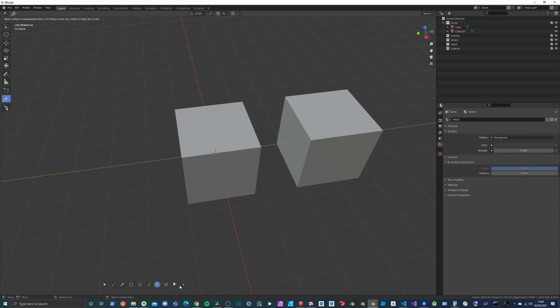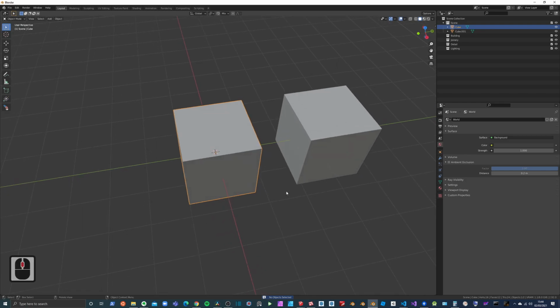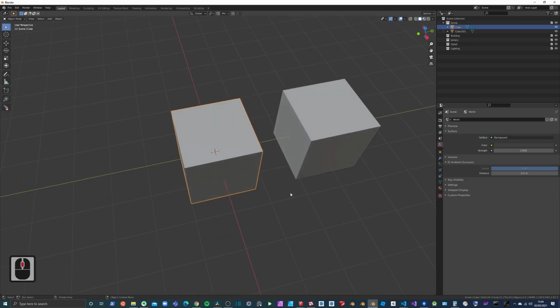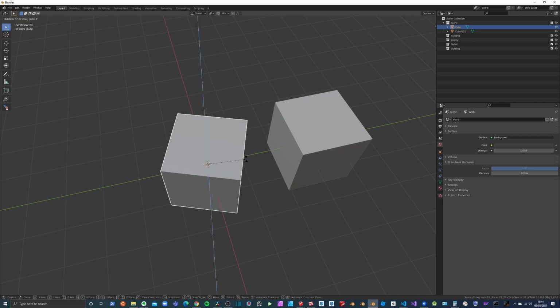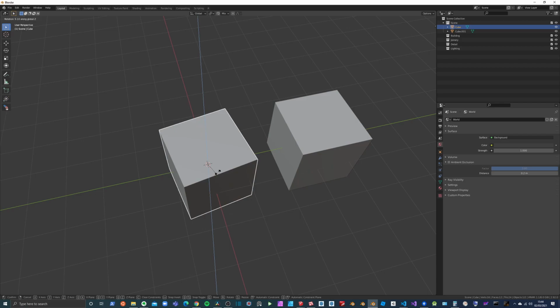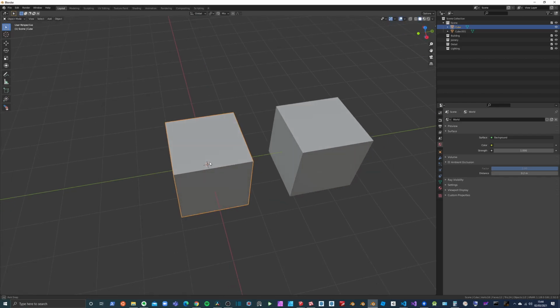So looking at rotation then, if I quickly skip back into Blender, as I mentioned in the last video, if you're new to Blender, the way rotations work is that if I hit the R key, I'll limit to the Z axis. All rotations take place around a specified pivot point, but you have to set that. So that might be the center of your geometry here.